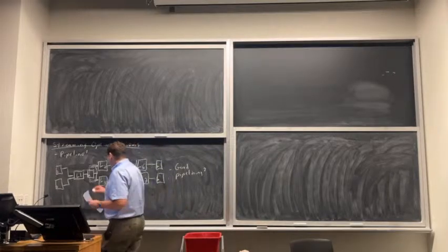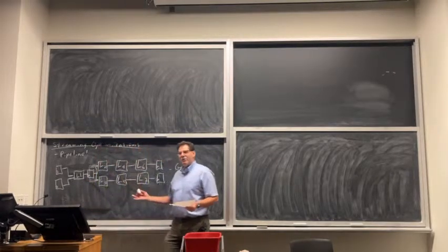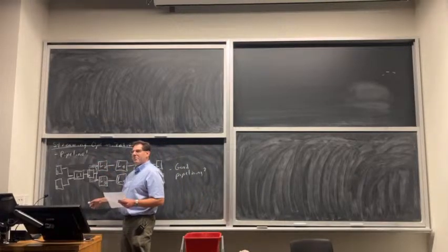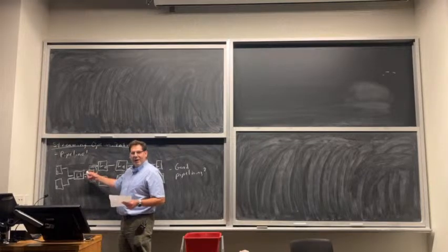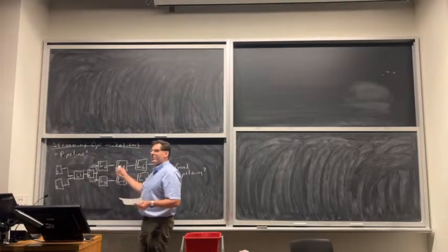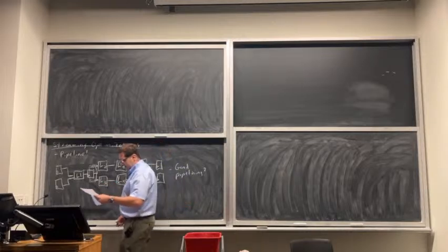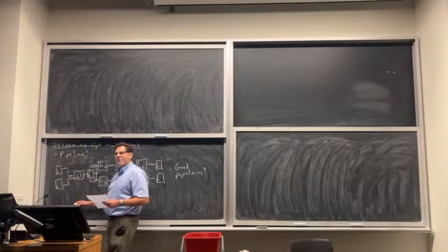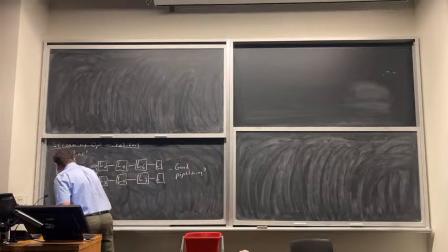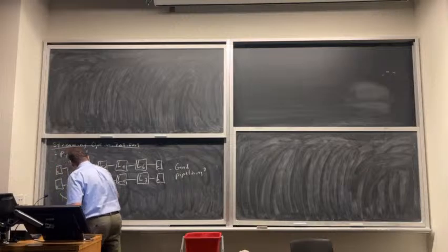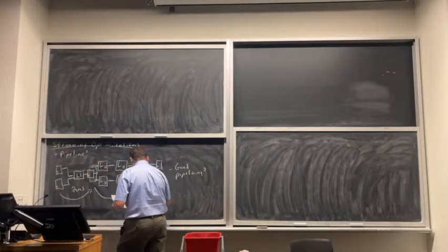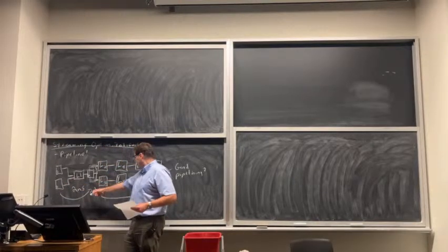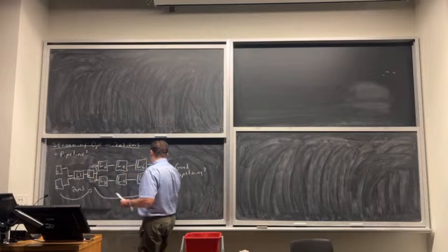Yeah, so I think you're basically pointing out that it doesn't look very balanced, right? One of the things we said with pipelining is it's good to cut where you're not going to make many registers. Well, we didn't make many registers, so it's very good from that point of view. But let's just do a simple delay model where every one of these lookup tables plus the interconnect for its output takes 2 nanoseconds. Which might not be correct, but let's just go with that. With that simple delay model, we got 2 nanoseconds delay from this register to this register, and we got 6 nanoseconds from here to here.